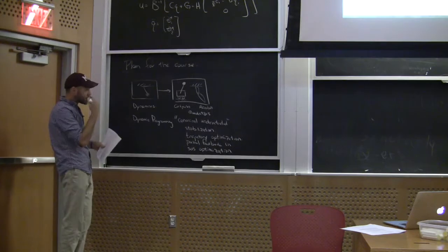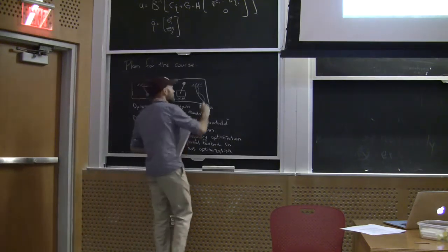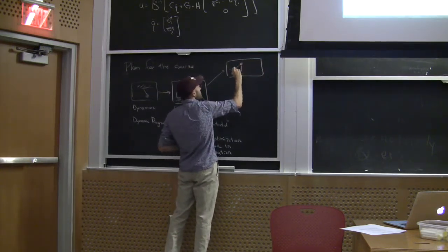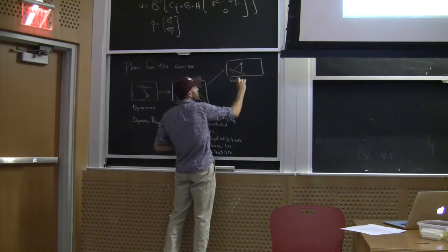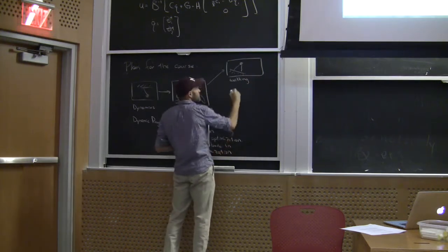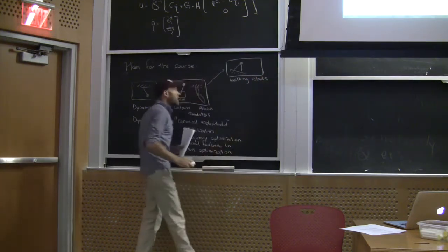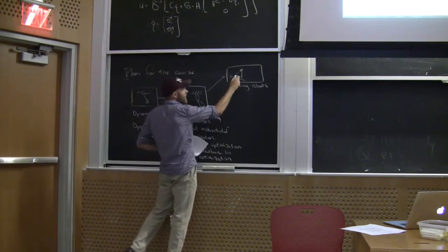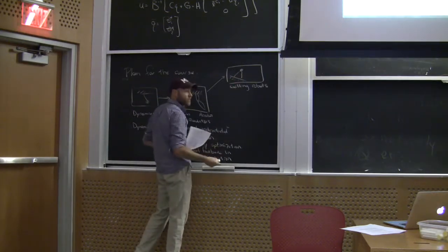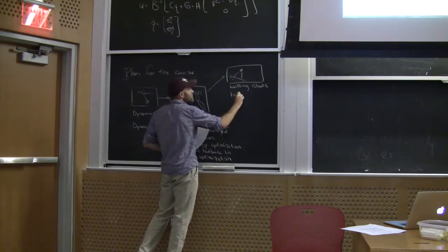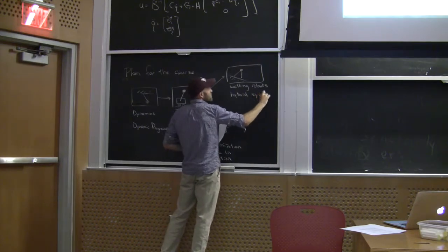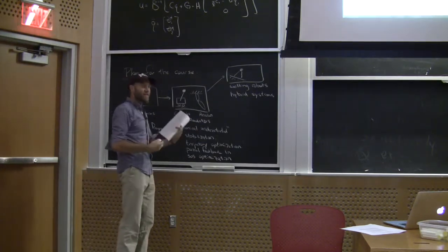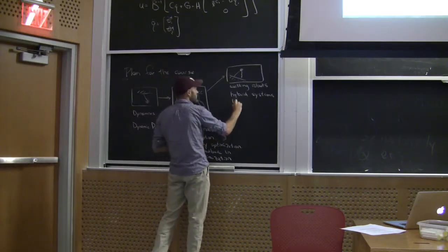Okay. And then the systems get more complex in a couple different ways. Because I love walking robots, we'll spend some time working on understanding the details of walking robots using both simple models and complicated humanoids. That's going to introduce us to some new challenges that come from having a system that's not only underactuated, but has impacts with the world. So you end up with hybrid dynamical systems. And we'll try to extend some of these tools to hybrid systems. Walking also gets us to talk about periodic behavior, limit cycles.